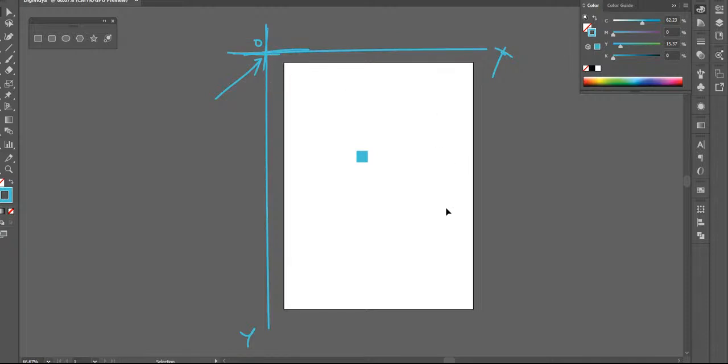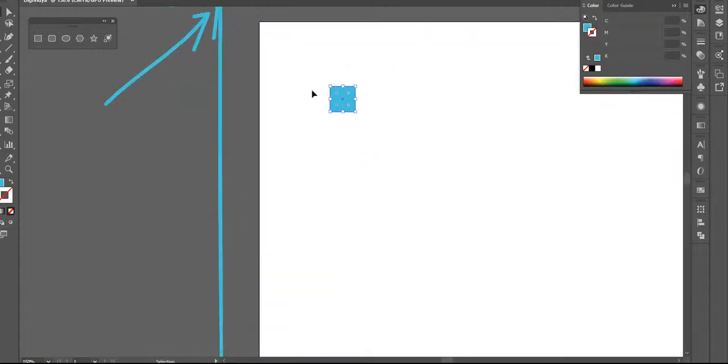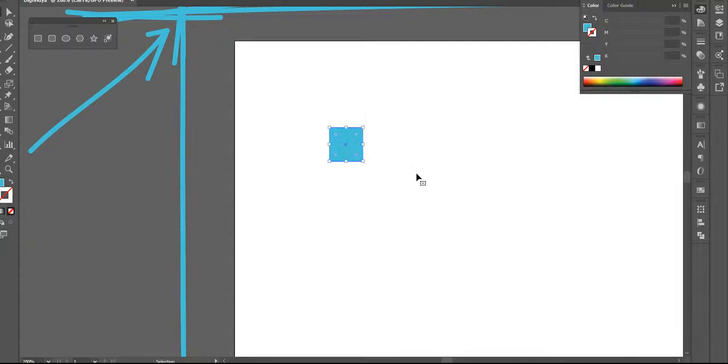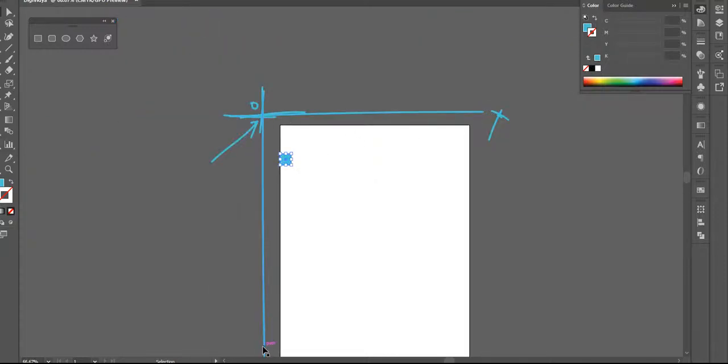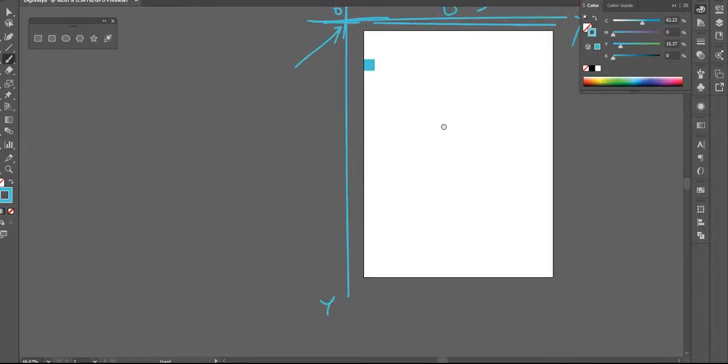So right now what I do, just look, the fun part of illustration is, I just select the square. Okay, go to the transform palette. Here I choose the reference point, so my top left is my reference point, right? And I press 0 here, x-axis 0. Look, this is my x-axis, this is my y-axis. My x-axis width is 8.5, keep in mind, 8.5 inches, and my y-axis is 11 inches.